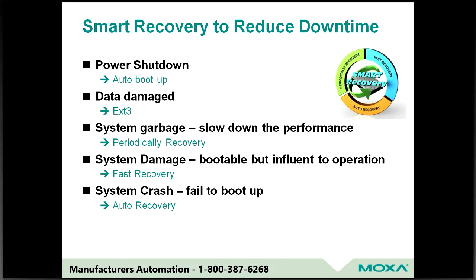Lastly, we're going to have smart recovery options. So say the catastrophe happens and your PC goes down in the field and you don't know what to do. Well, a high quality industrial HMI or panel PC will have an internal memory log, so that if it's shut down for any reason, it's rebooted, and the memory and data logs within that computer are going to be time series backed up to a set date and time. You could have an auto log for every day.